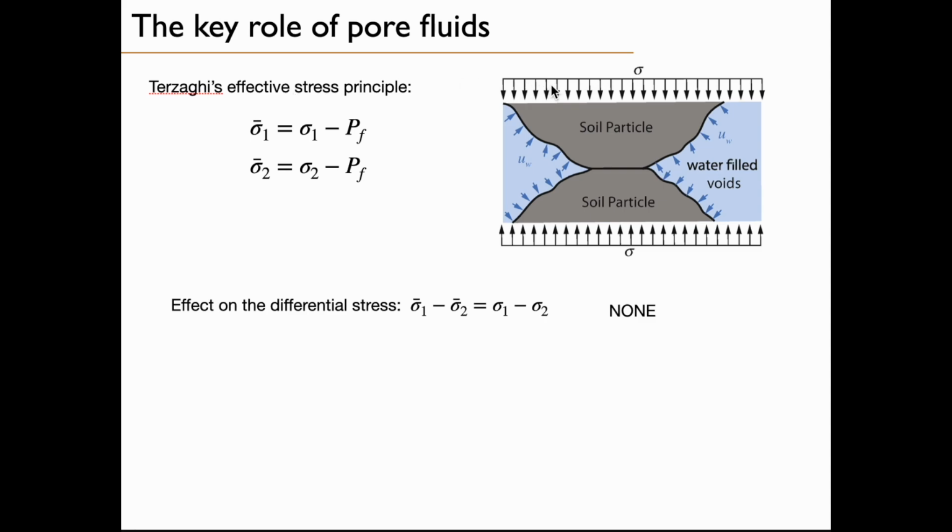So now you have to think about a volume of rock. We zoom into the rock, we have some particles of soils or rock, and there are some pores, and the pores are full of water. That's water saturated, and the water is incompressible. So when this rock is under stress, the solid particles will deform. They are a bit compressible, so we can deform the system, but the water cannot deform, so the pressure will increase, and this will have an effect.